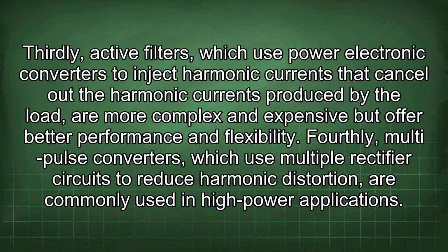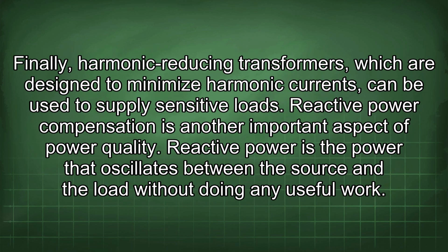Fourthly, multi-pulse converters, which use multiple rectifier circuits to reduce harmonic distortion, are commonly used in high-power applications. Finally, harmonic reducing transformers, which are designed to minimize harmonic currents, can be used to supply sensitive loads.